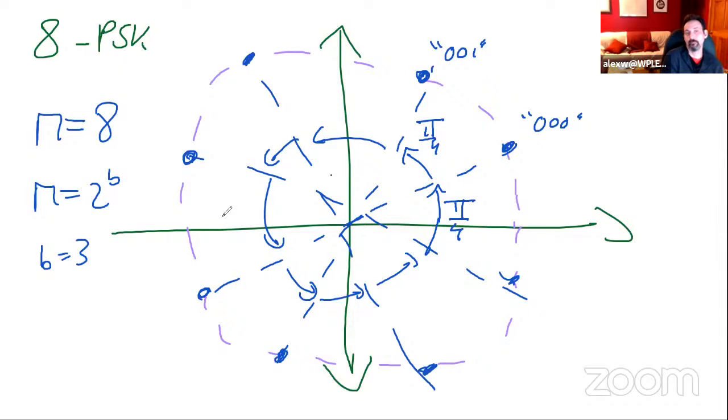Okay. So the beautiful thing about PSK is that the modulation stays the same, the amplitude stays the same, the frequency stays the same, but the phase changes. And this is how we represent it in the IQ plane. So this is how we use the vectorization of a modulation scheme, and as you saw in the projects, this is how you see when you have a clean signal and when you have a signal with an unpleasant amount of noise. Okay, so let's go back to the slides.